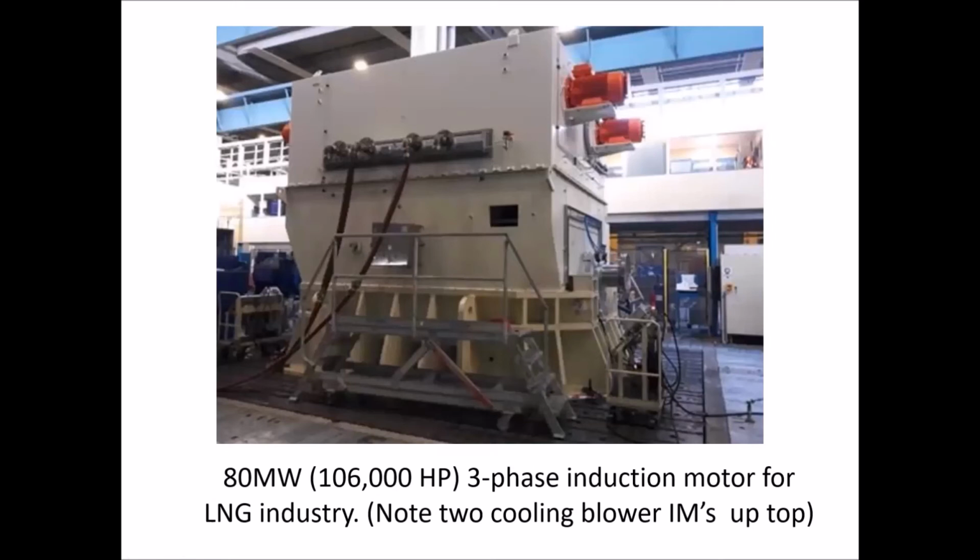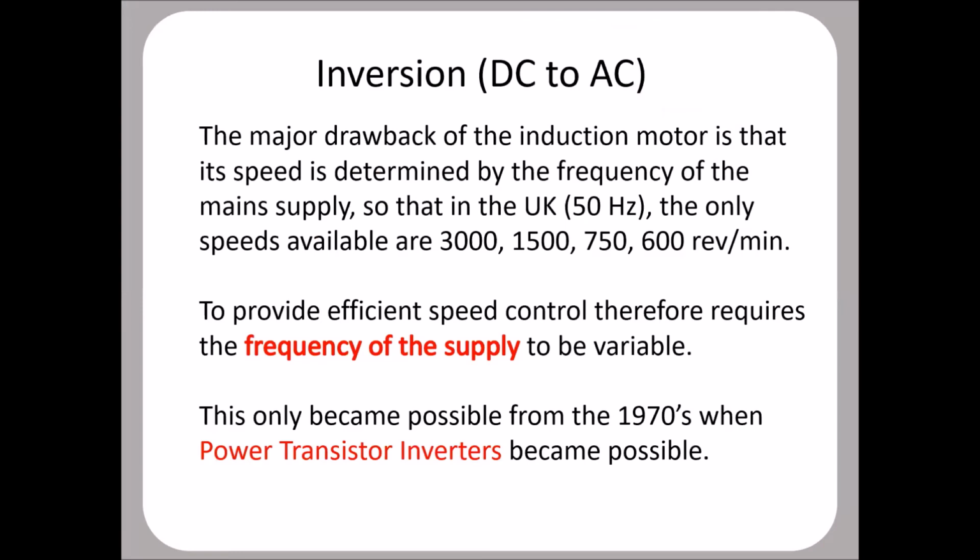The major problem with the induction motor, see here, it only runs at a fixed speed. Well, having said that, you do have a choice of speeds, as shown there, 3,000, 1,500, whatever. But there's no way you could run it by just connecting it to the Yorkshire electricity and give you an in-between speed. The only way you could provide efficient speed control is if you can create a variable frequency supply. Well, it's no good bringing up the national grid and saying, oh, I want to go a bit slower. Can you slow down from 3,000 to 2,000 revs per minute for all your generators? No, of course not. We have to be able to create an AC.